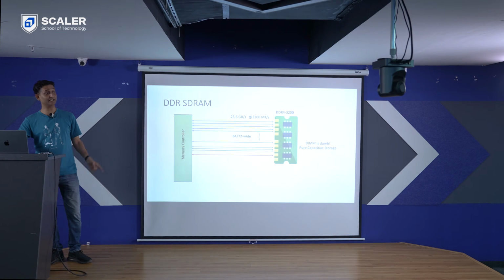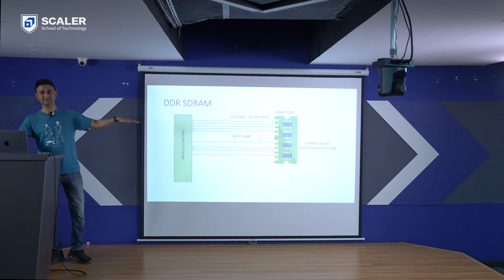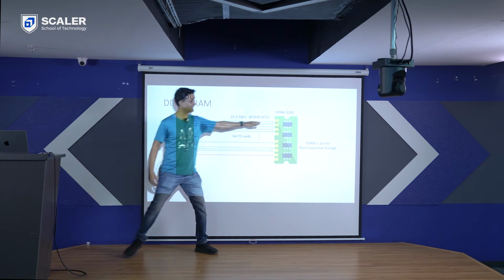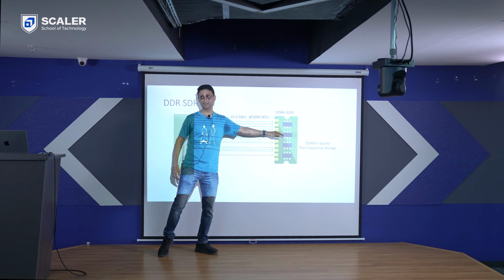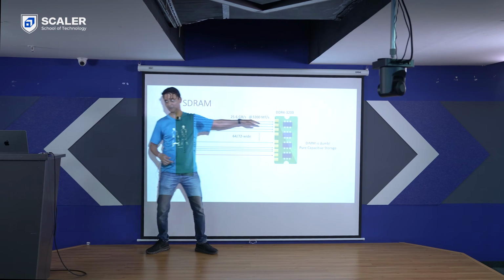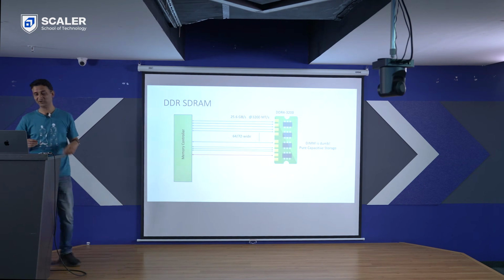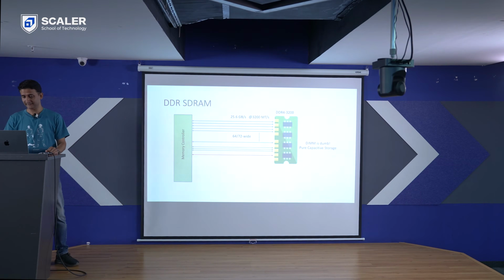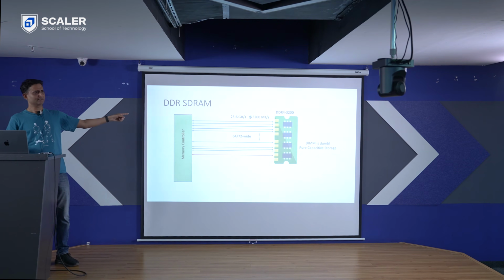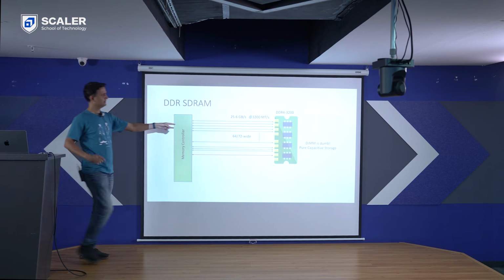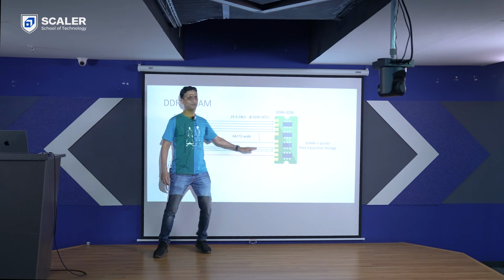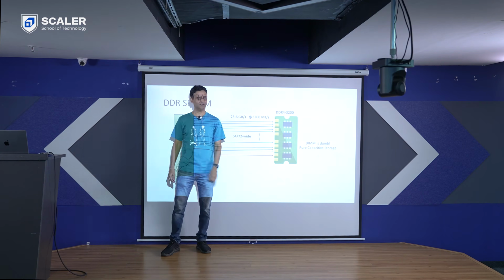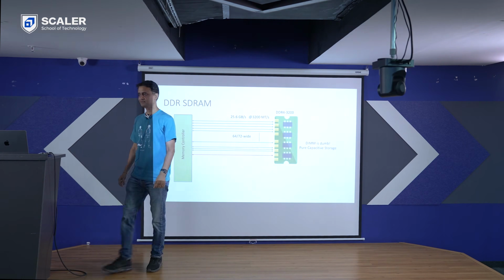By the way, DDR5 includes on-die ECC. So if this were a DDR5 stack, on the die itself you have ECC. Food for thought: would the link require ECC or not? Or can things get corrupted during the link? So if the question is, no matter how many transfers per second, why should I not have, like, 128 bits wide? Cost.